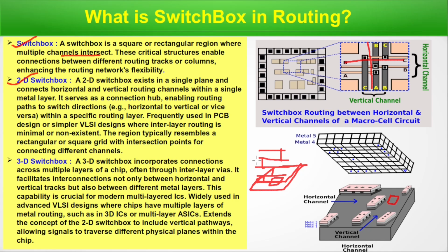A 3D switchbox. A 3D switchbox incorporates connection across multiple layers of a chip, often through interlayer vias. It facilitates interconnections not only between horizontal and vertical tracks but also between different metal layers. This capability is crucial for modern multi-layered ICs. This is shown as a 3D structure, metal 5, metal 4. So here if we consider, it's a 3D switchbox.